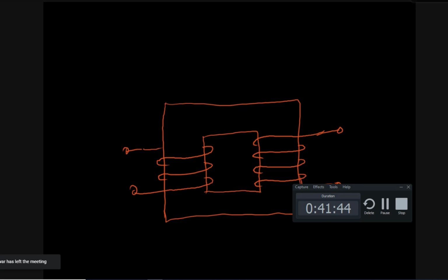Leakage flux has several other connotations and problems. To minimize that, both the primary and secondary windings are wound on a single central leg, one above the other. Primary will be inside and the secondary will be above that one, with adequate insulation between the windings.